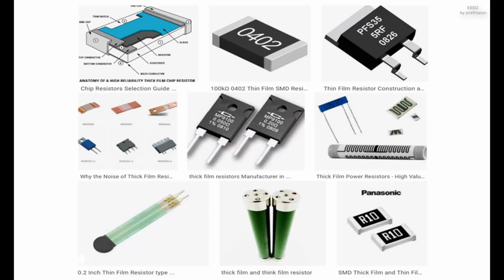Thick film resistors may use the same conductive ceramics, but they are mixed with sintered, powdered glass and a carrier liquid so that the composite can be screen printed. This composite of glass and conductive ceramic, cermet, material is then fused, baked, in an oven at about 850 degrees Celsius. Thick film resistors, when first manufactured, had tolerances of 5%, but standard tolerances have improved to 2% or 1% in the last few decades.